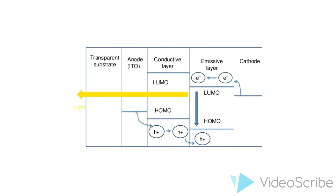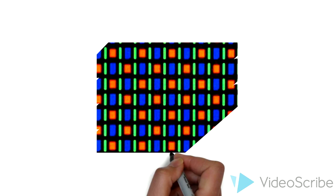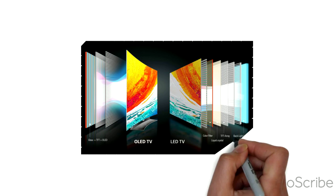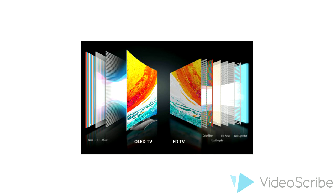The frequency of the light is dependent on the difference of energy between the conductive layer polymer's HOMO and the emissive layer polymer's lowest unoccupied molecular orbital, or LUMO. By combining thousands of individual red, green, and blue OLEDs, these will together function as pixels to create a high-resolution picture, as we see in high-technology televisions right now.